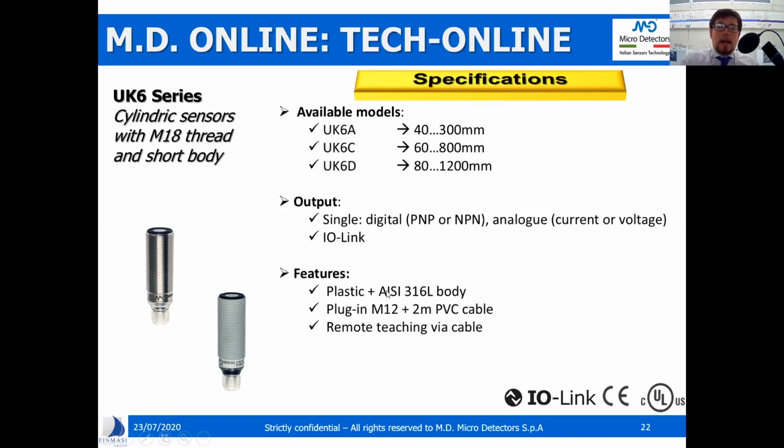Also in this case, we have both plastic and metal housing models, and about the electrical connections, both M12 plug-in and cable models, but a difference with respect to the standard body, because in this case we have no teaching button, but we have a remote teaching via cable, and we are going to show you how to adjust a UK6 sensor.